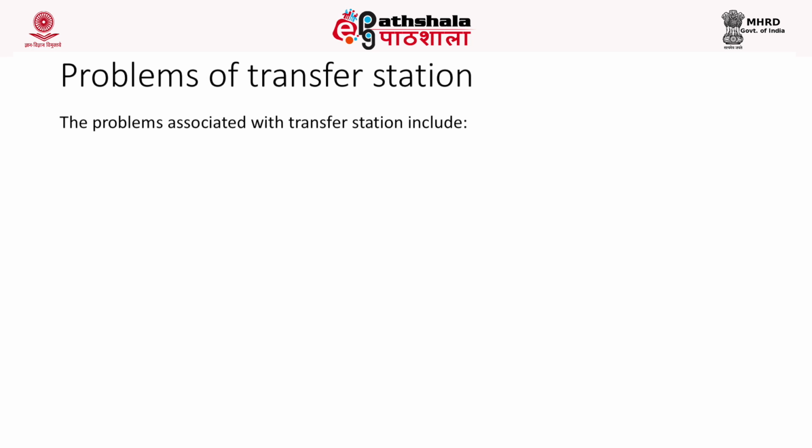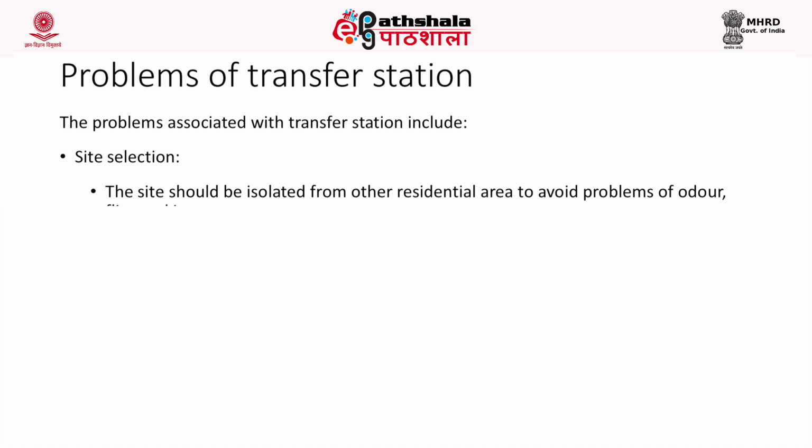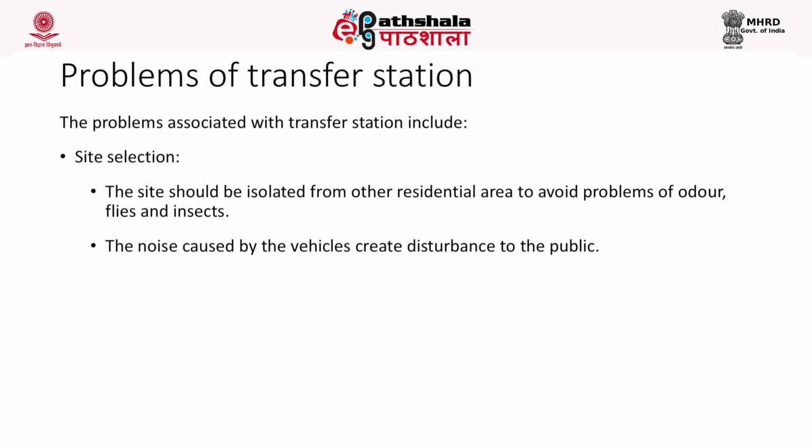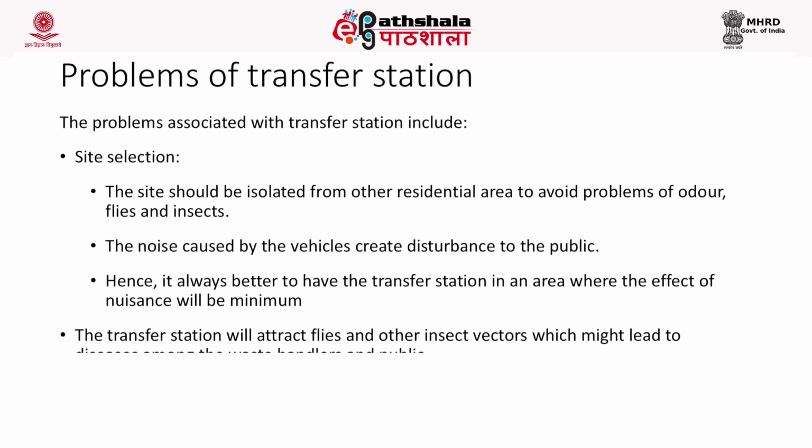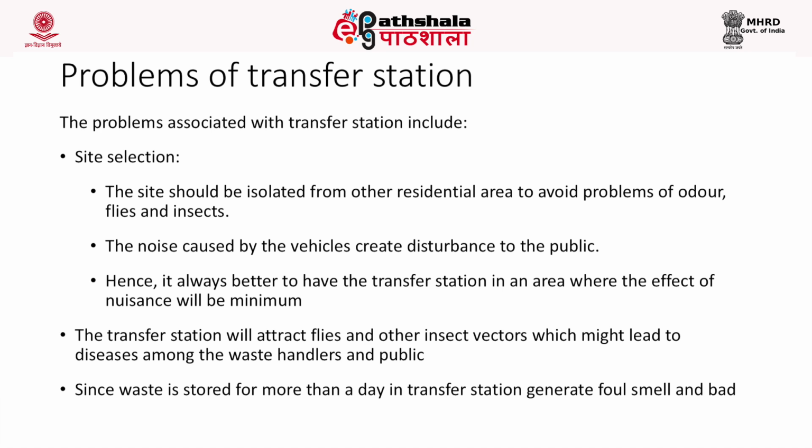Now, there are a lot of problems which are associated with this transfer station. Let's look into the various problems that are associated with this transfer station. First, site selection. It is essential for us to choose a site which is generally isolated. The site should be isolated from other residential areas to avoid problems of odor, flies and insects. The noise caused by the vehicles creates a huge disturbance to the public. Hence, it is always better to have a transfer station in an isolated area so that all these